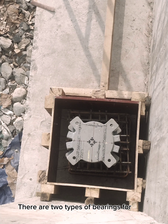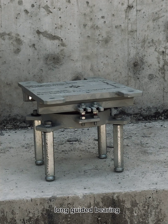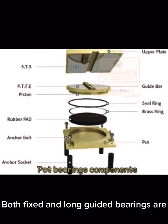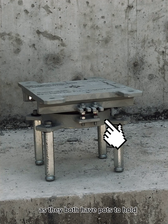There are two types of bearings for the upstream side and the downstream side. For upstream side we used fixed bearing, and for the downstream side we used long guided bearing. Both fixed and long guided bearings are a type of pot bearing, as they both have pots to hold the components within.